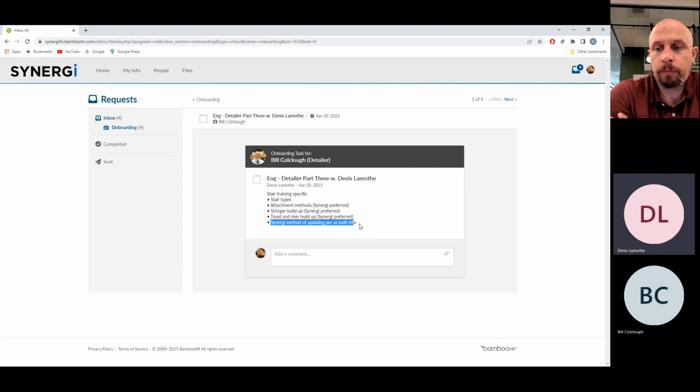Specifically, we'll be looking at updating for as-builts. That includes field dimensions, whether it's point cloud or any other kind of field survey that's given. Sometimes it's just an old-fashioned tape measure and a laser level, and we're handed a sketch and we go from there. We'll review quickly how we incorporate those field surveys and any markups from clients and engineers into our final submittal drawings. And I think that will be the gist of what we'll be reviewing today.